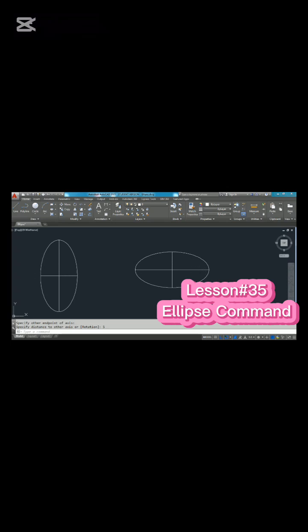And I would like to tell one more thing. We don't have to have the major axis and minor axis drawn using lines. We can directly pick points on the blank screen. Let me show that one also. Type EL at the command prompt and pick the endpoint of the first axis and drag your cursor. You can enter the length of the axis also at the command prompt. Let me show you that one.